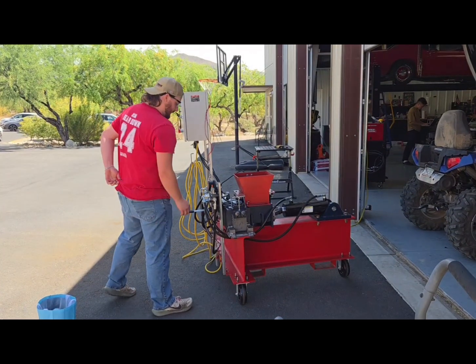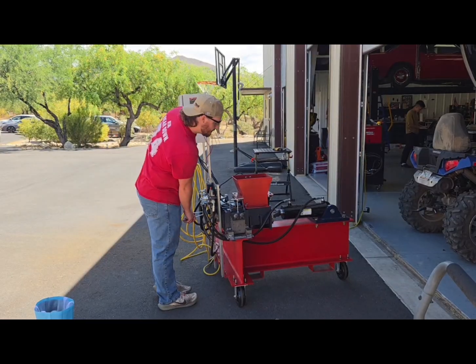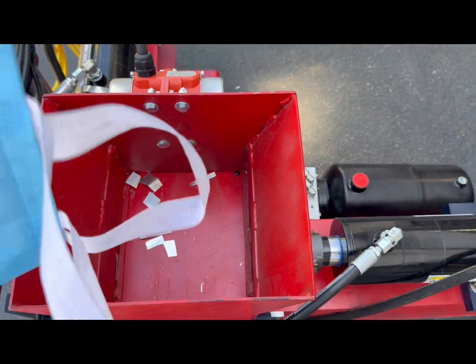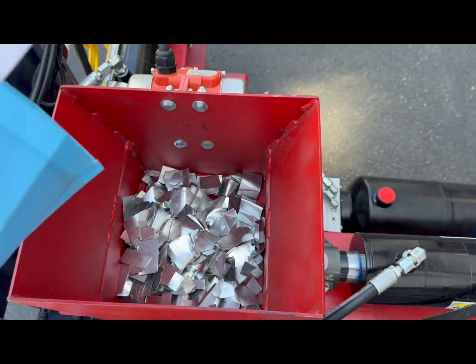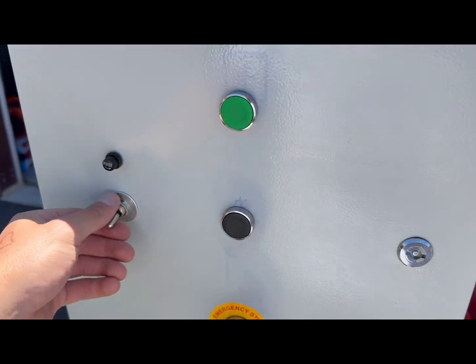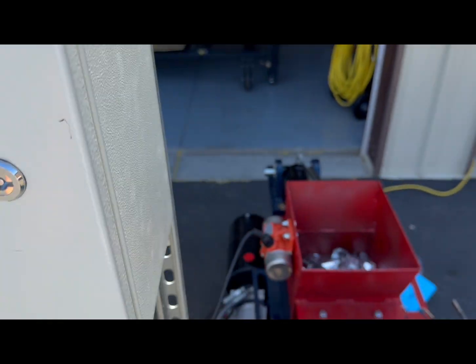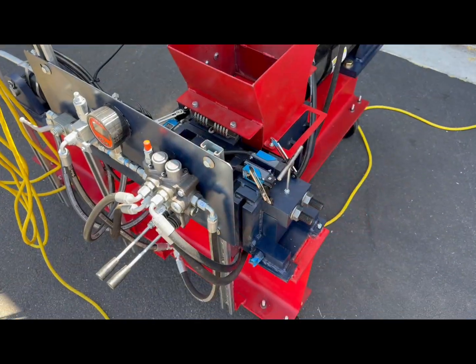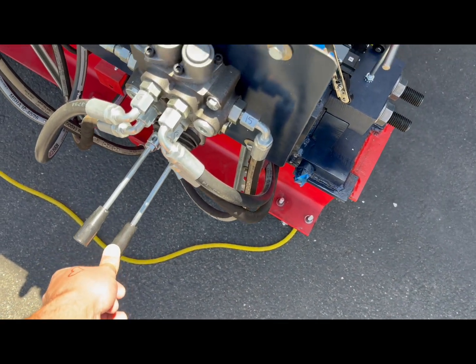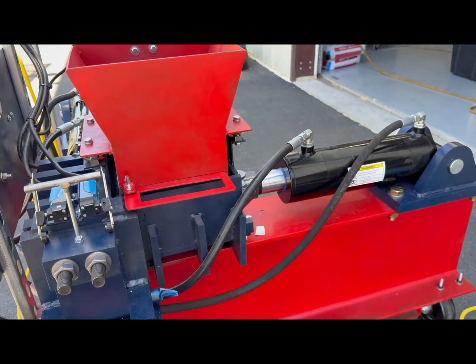In this section, we're demonstrating the full operation of our aluminum baler. We start by loading the loose aluminum scrap into the hopper. At this stage, the material is irregular and contains a lot of empty space. Next, we turn on the vibration motor. This helps the material settle, redistribute, and allow smaller pieces to fill in the gaps and improve packing before compression. After a few seconds, we turn the vibration off and allow the material to fully settle into the chamber.